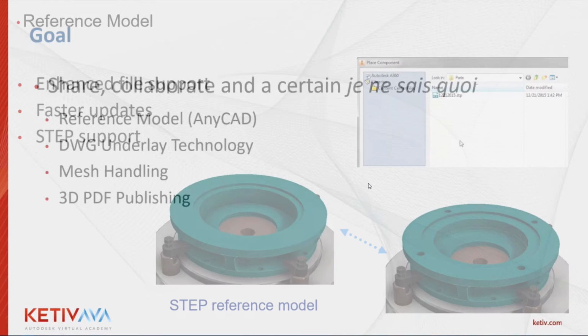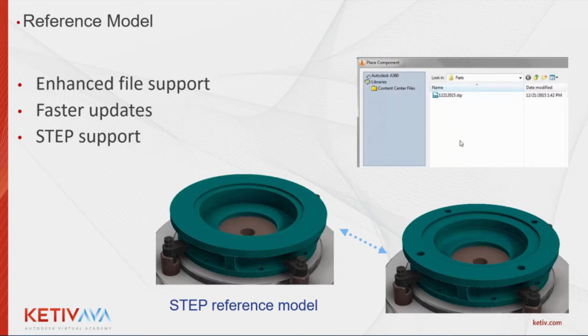And of course, I'm French, I'm from Montreal, so I had to have a little je ne sais quoi in there as well. So I'm going to start with something we call referencing the model, aka AnyCAD. AnyCAD came out last year with the 2016 release. It is, to put it simply, because I don't have enough vocabulary, just crazy and amazing. We can open SOLIDWORKS, CATIA, NX files as is. We don't have to convert or translate them. They're going to live inside our Inventor assembly the way they should be. We're not converting them. So instead of talking, let me show it to you.